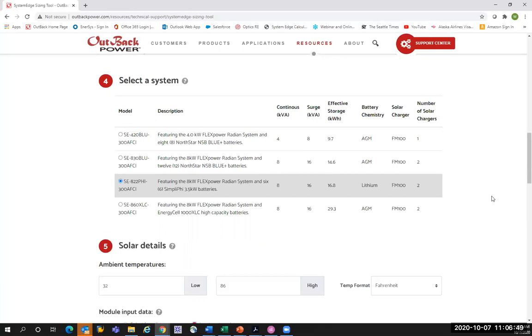But in terms of the sizing, if you were to size just for that 100 milliseconds of inrush current, you'd have an inverter system that was just way too big. And so we found that by using a factor of 3, when the actual inrush current might be more like a factor of 7, you're probably going to be okay, just because you're sizing for all these other loads in the system.